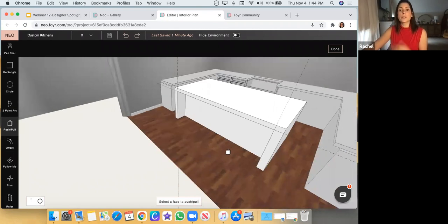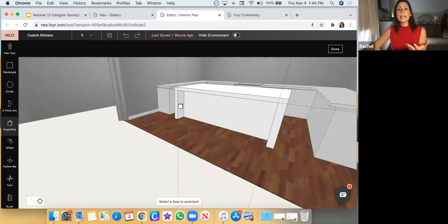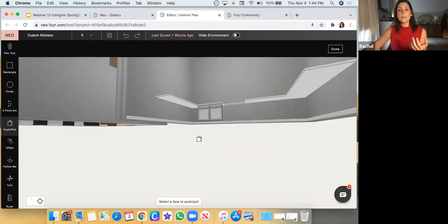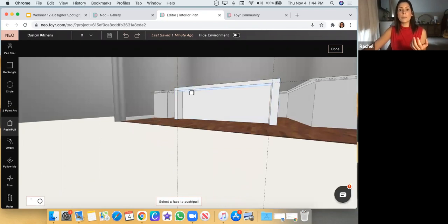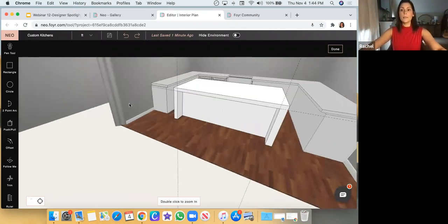And what's so nice about doing this with Create New Product is that each one of these planes is a separate plane that you can also apply a different texture to. So again, another benefit of Create New Product is that unlike a cube, like one of the white cubes, which the texture would apply uniformly to all sides, with Create New Product you'll always have the option to define every single plane. And I click the escape key.